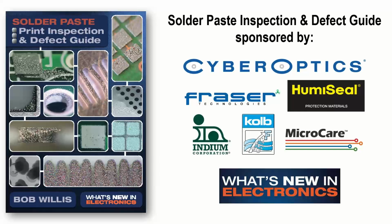So you tell me. If you get an infrared camera and try it out on your printer and run it up and down the stencil a few times, it's not something that I've been aware of or experienced myself, but I'd be fascinated to learn if you do some measurements. So all you need, go down to your maintenance department, ask them to borrow, if they've got an infrared camera, and check the stencil temperature, check the paste temperature, and then check the blade after you've printed, let's say 20 times, just as a kneading stroke, and see if you can see anything. I'd be fascinated to. You've piqued my interest now to see if there's anything there.